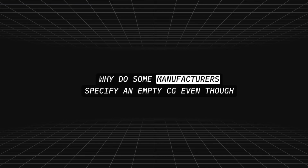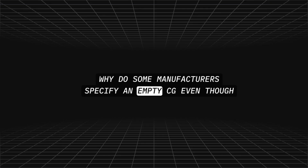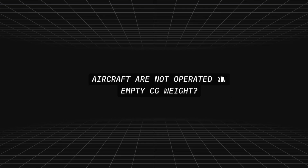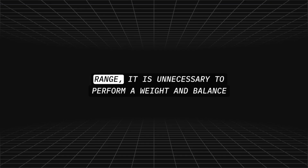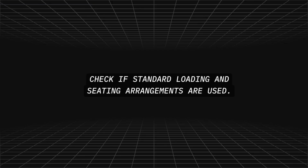Why do some manufacturers specify an empty CG, even though aircraft are not operated at empty CG weight? When the empty weight CG falls within the empty weight CG range, it is unnecessary to perform a weight and balance check if standard loading and seating arrangements are used.